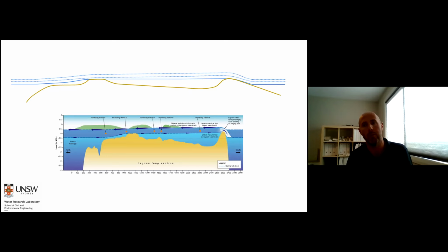So even though the community was wanting to dredge that passage because they know that's where currents discharge from the lagoon, that's actually not the controlling feature. The controlling feature is a shallow area within one of the lagoon channels. So dredging further north would have absolutely no impact at all on the lagoon flushing further south. And we were able to answer that quite definitively with the data.